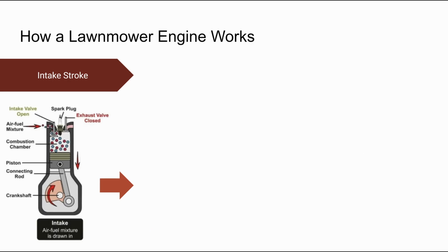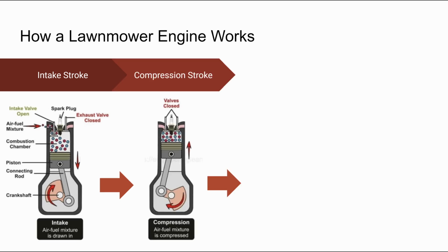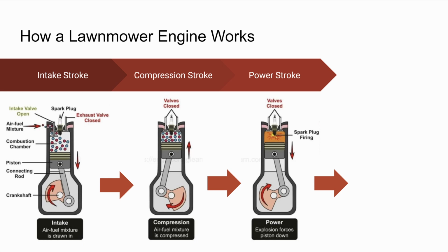First, air and fuel enter the carburetor and into the combustion chamber of the engine. Atmospheric pressure forces the air-fuel mixture into the cylinder bore and the piston moves downward. Next, the intake valve closes and the piston travels upwards, compressing the air-fuel mixture between the piston and cylinder head. Then, the piston reaches the top of its travel. A high voltage is created in the ignition, and the spark plug discharges the voltage into the combustion chamber, igniting the gases and forcing the cylinder back down.